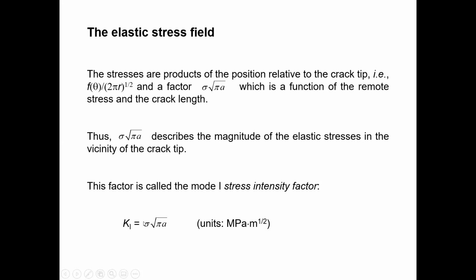Okay, so you can see there is no delta part now. If you want, you can put it, but delta and sigma are not different. You will use one single value as a constant. So in that particular case, if the stress range is 60, you will substitute 60 megapascals. That's all. So the mode 1 K I value is the stress intensity factor mode 1. In here, this is not a 1, okay, this is I. Stress intensity K I, that's only how they put it, as mode 1. That is the meaning of mode 1. Stress intensity factor K1 or K I equals sigma times this one, okay, on the factor.